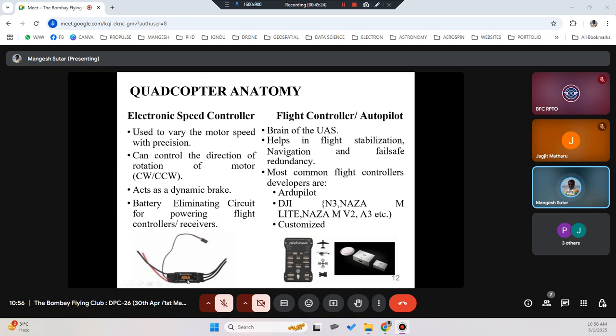तो 25 amperes के ऊपर, 25 एम्पियर का ESC लगाओगे तो क्या होगा, वो गर्म हो जाएगा. या उससे कम वाला, like 20 amperes का लगाओ तो क्या होगा, it will fully load the ESC. The chances of your ESC catching fire और burn out होने का chances तभी है. So to safeguard your ESC, you will always use a higher capacity ESC. Clear on this concept? What ESC to be used along with the motor as well as the propellers?